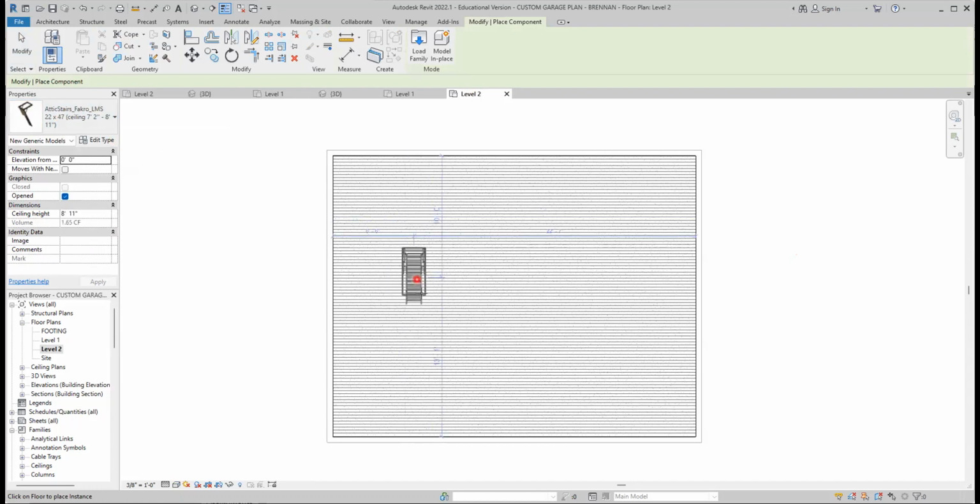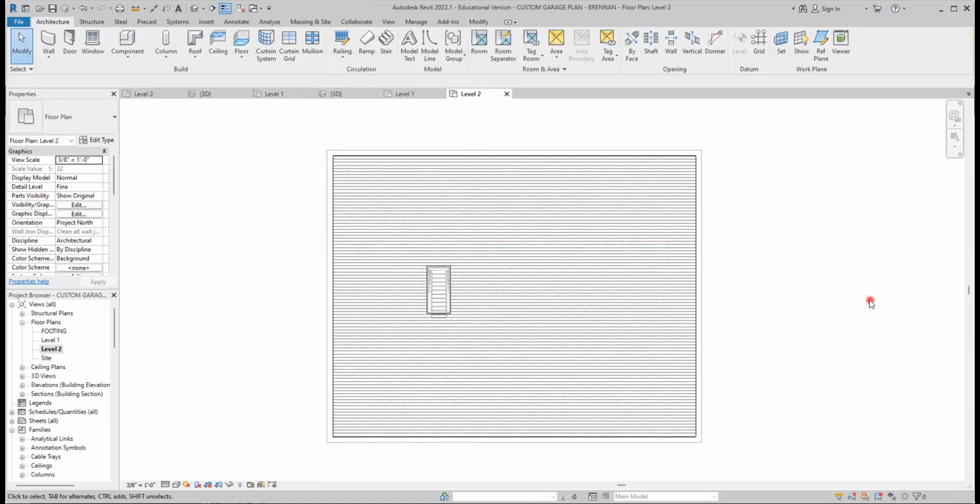So we're going to drag our cursor right here, and can you guys see the attic stairs right there? Okay, you're going to take them and drop them somewhere right around here. Just drop them right in position, and we're going to leave them right there. We're going to position them later. But for right now, click the modify arrow to get rid of it. So we have just placed stairs in here. Now, to rotate them, you can't rotate them from this floor. We have to go down to the first floor.